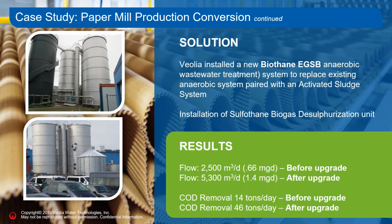So this is a client where we have worked for 25 years. Initially we had a UASB system on site, and after they did their conversion, we upgraded the whole facility with a BioBed EGSB process. On the pictures on the left-hand side, you can see those are stainless steel reactors. In this case, the biogas is also treated to get to a quality for use. The system is then followed by an activated sludge, as in this case there's no MBBR, but there's a conventional activated sludge system.